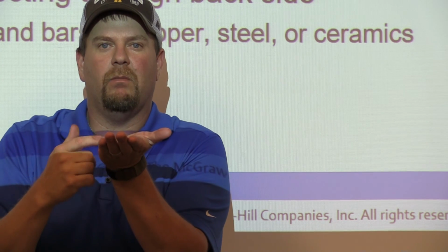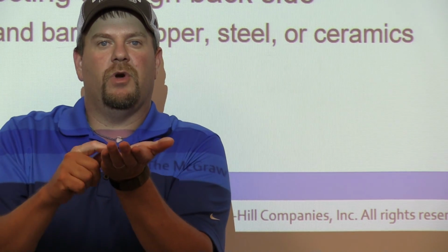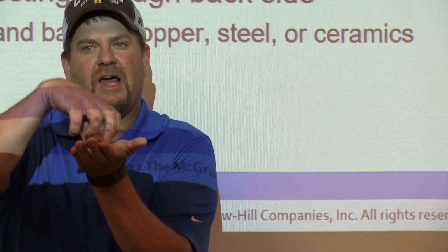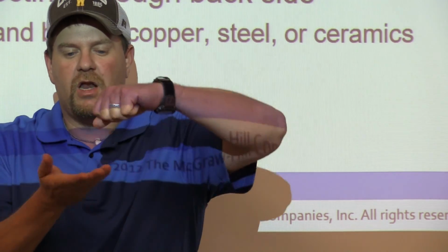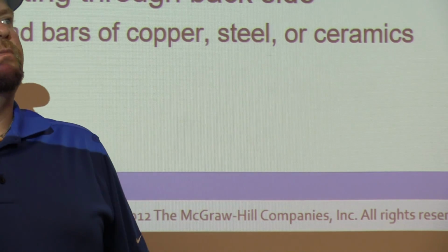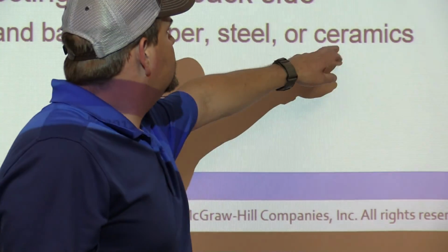Basically it's like a backing bar or a chill ring, and it won't fuse to it, it'll just lay against it and solidify, okay? And I would just kind of move it along that weld joint as I was welding along. And that kind of became my backing strip or my backing bar. You can do it in ceramics,